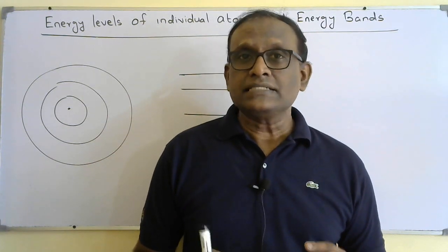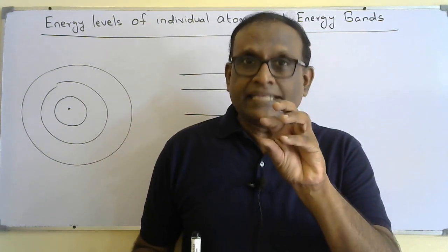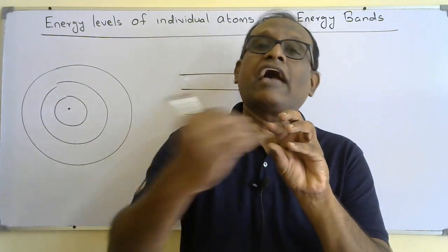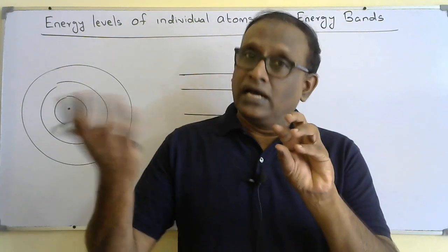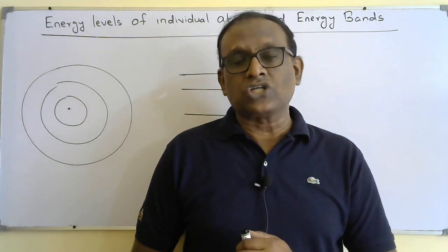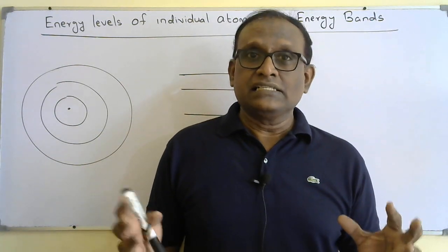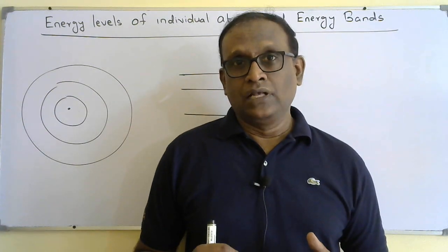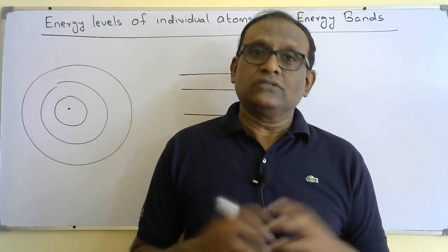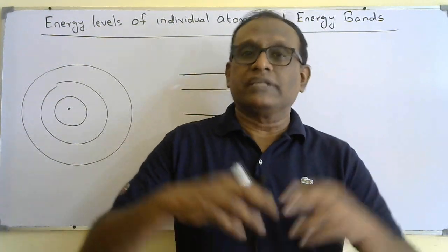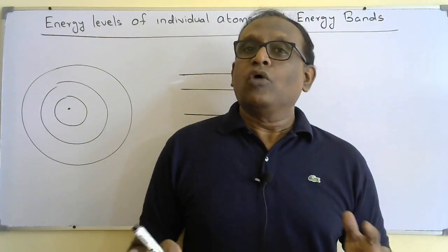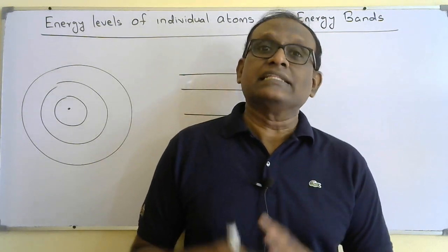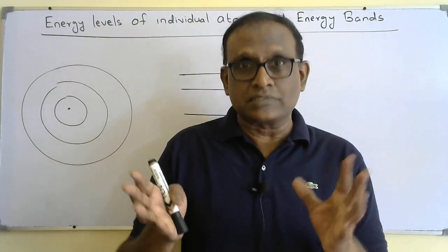But in solids, what happens? If you think about a specific atom, all the neighboring atoms will have an influence on that atom in terms of electrostatic force. So the energy levels are closely packed together and overlap with each other. Due to the overlapping of energy levels of the neighboring atoms, when we think about electrical conduction, we don't consider the individual energy levels of atoms in solids.